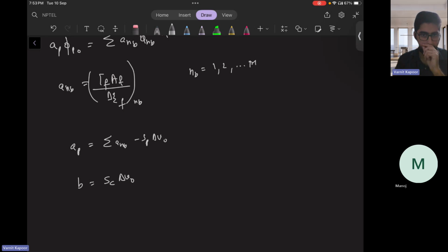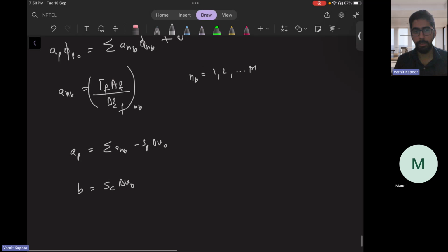Great. I know it's a bit heavy, but if you practice writing all this with your hand, you will find it easy. So first we have seen what is an orthogonal mesh: the area vector is parallel to the line joining the two cell centroids. It will not work if the cell centroid lies outside. It will definitely work in 3-dimensional.